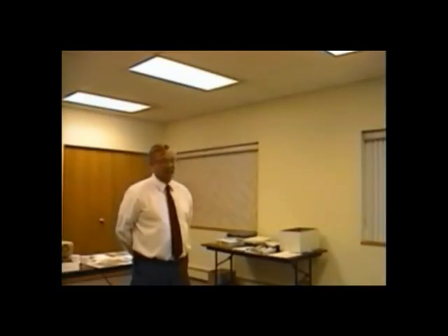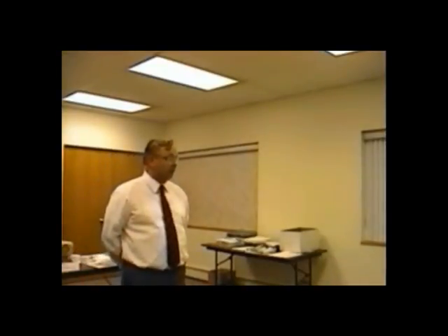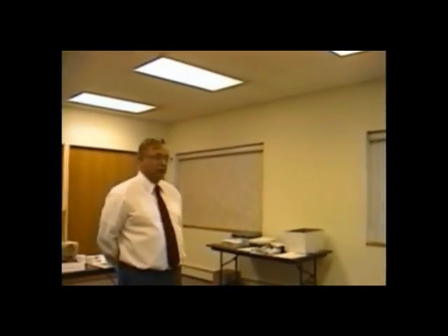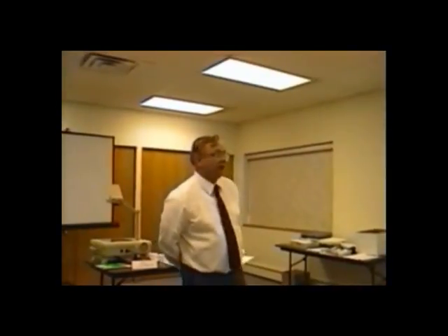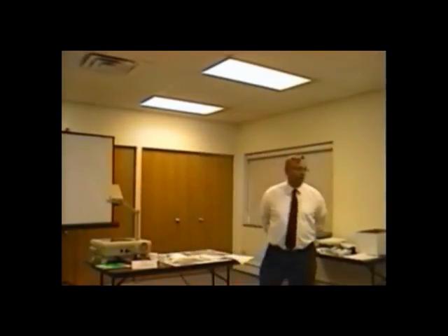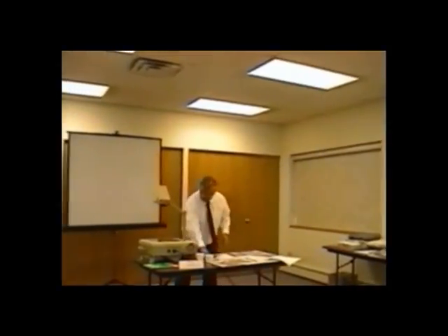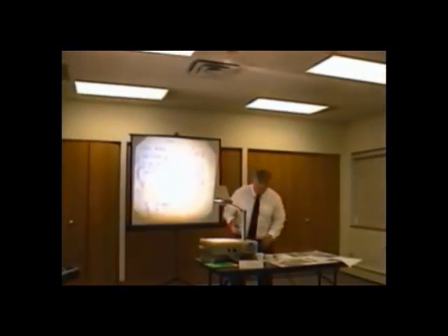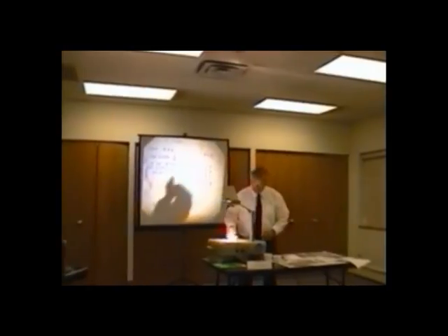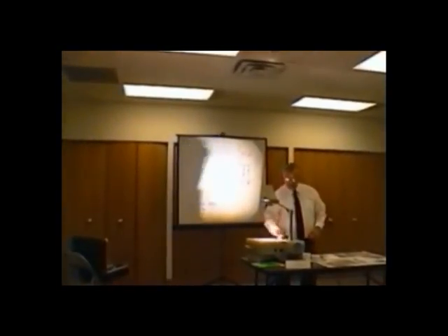Now look for other things, like ductwork, dirty A-coil, dirty condenser, dirty secondary coil on a 90-plus furnace, dirty blower wheel. But you don't have to alter the charge. Isn't it neat? But you say, yeah, are we okay with this? Can I erase this one? Mm-hmm. You okay?